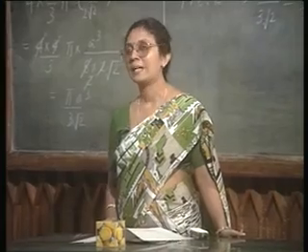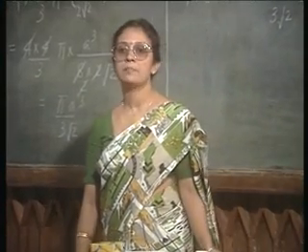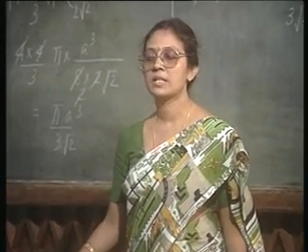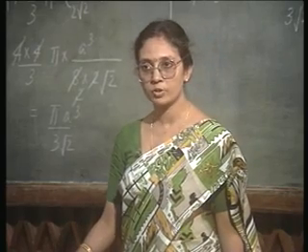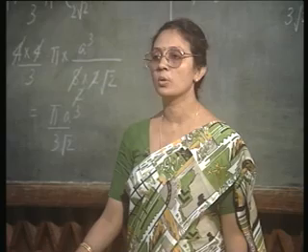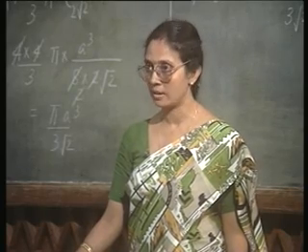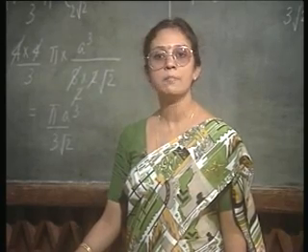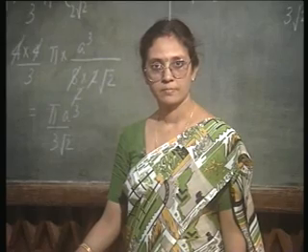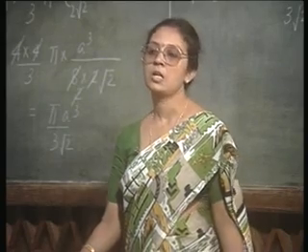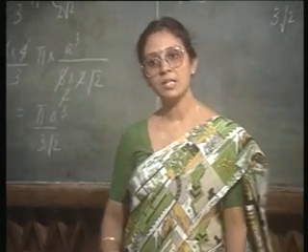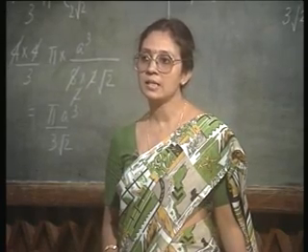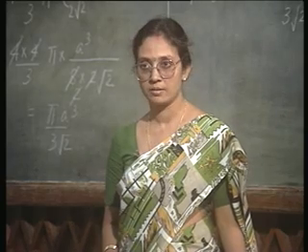atom. Now, silicon has a particular tetrahedral radius. Just now we have said that it has a lattice constant of 5.43 and therefore, its tetrahedral radius works out to be 1.18 angstrom. The impurity atom may or may not have the same tetrahedral radius. So, what will happen? If it does not have the same tetrahedral radius, then you can introduce strain in the lattice. The lattice will be strained.